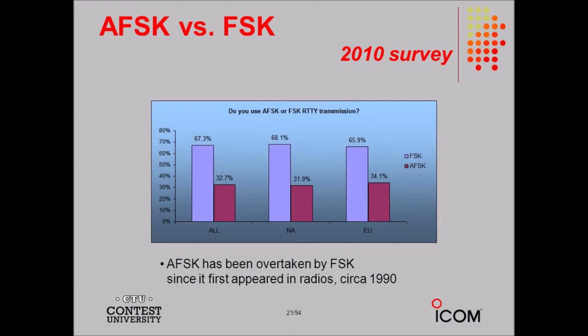The space between dots and dashes within a character equals 1 bit. The space between characters in a word equals 3 bits. The space between words equals 7 bits. Some technicians refer to the key down, full carrier, condition as mark, and the key up, no signal, condition as space. Amateur radio operators who enjoy using the Morse code send and receive it at speeds ranging from about 5 words per minute to around 60 words per minute.